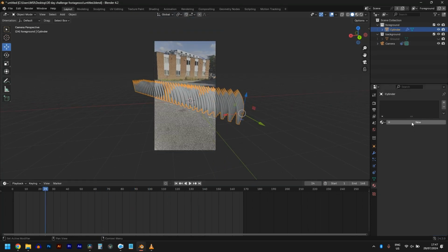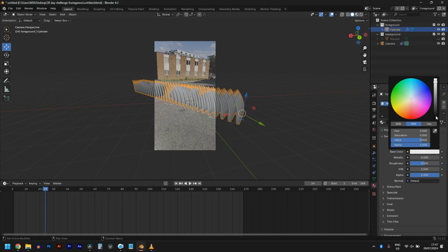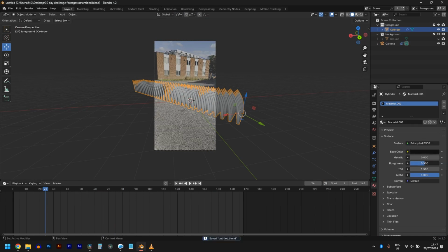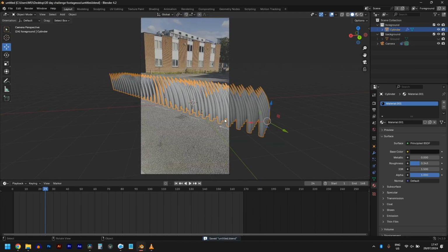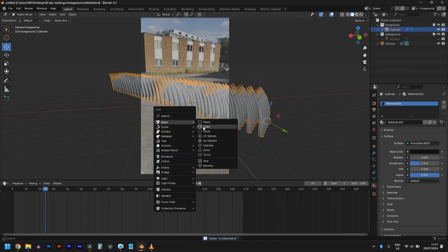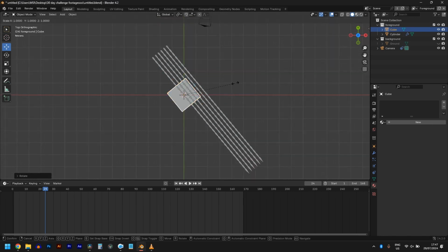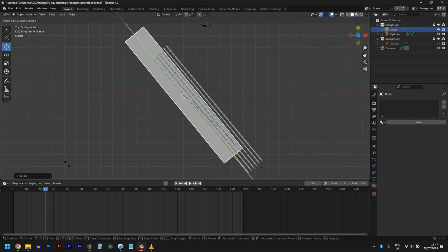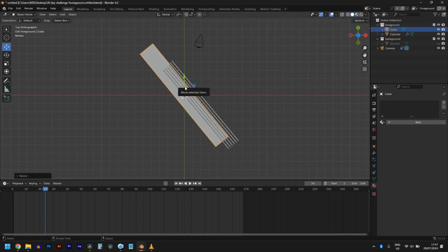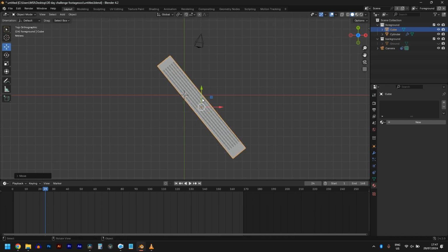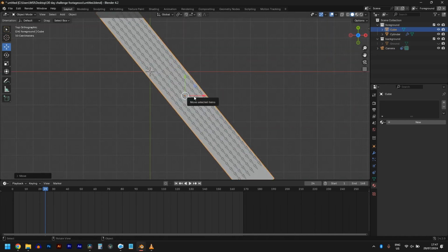Let's go to material, new, make this black. Just a black, maybe reduce the roughness a bit. Now let's add a cube and rotate it on the Z axis and scale it on the Y axis. So this was just something I added in the end that's going to serve like our skin, because I searched for reference of what hair follicles look like and I realized that they shouldn't grow out of the road, because that was my initial idea.